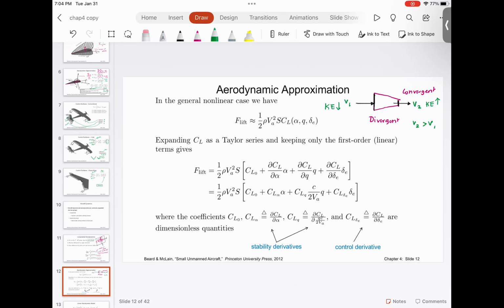For conservation of energy, total energy is going to remain constant. So what it means is, in fluids, you have three types of energies. You have a pressure energy, you have potential energy, and you have kinetic energy. Pressure energy, potential energy, and kinetic energy. Please understand that this nozzle is at the same level, which means the potential energy is going to remain the same at inlet and exit. You agree with me?